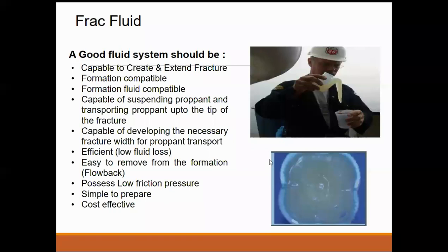Okay, because if you want to flow back the same high viscosity fluid that you have pumped, it will also bring the sand back with it, which you do not want. So the viscosity is to be broken first. So these breaker chemicals are added into the frac fluid so that the viscosity can break and you can recover just the broken fluid. Now, when the fluid is broken, it might produce some solid residue, which can damage your proppant pack permeability, which you have created after fracture. So you don't want that, right?